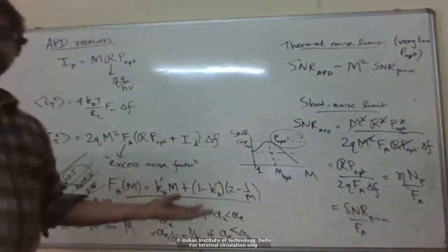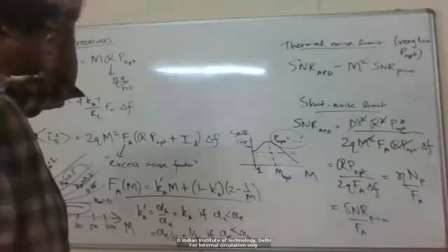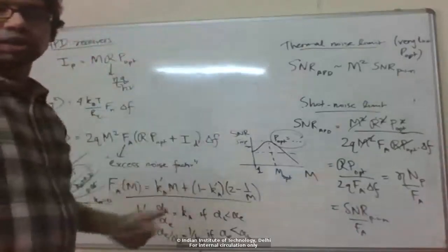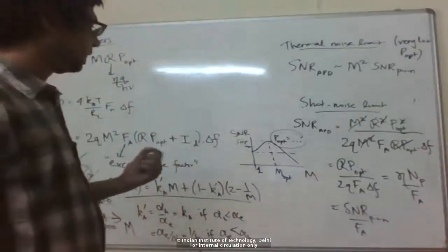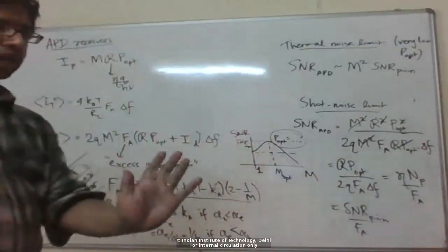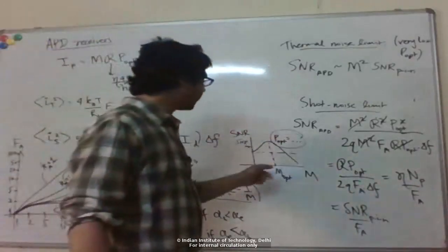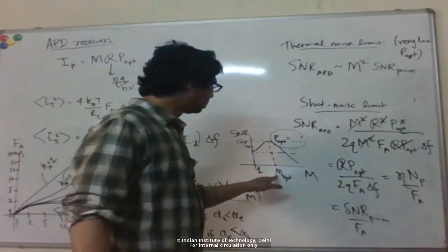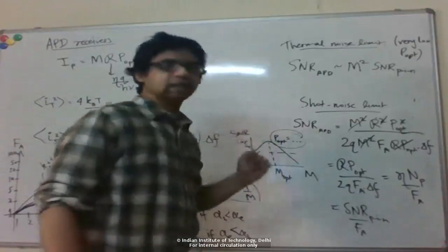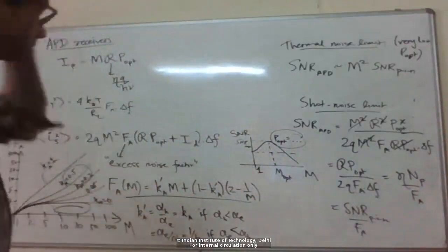Okay, so if I have an optical communication link and I know how much power is being sent at the transmitter, I budget for all the losses along the link, then basically I know what optical power I will get at my photodetector at the receiver, right? So if I know this, then I can use a detector with this optimum gain to get the maximum SNR and consequently the lowest bit error rate.